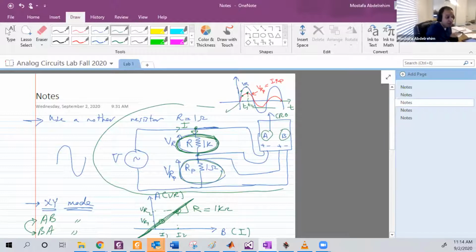And we must put here a variable signal, because we want automatic drawing. So we want the voltage to change by itself without our intervention. We are not doing step by step. So we're gonna choose, for example, a sine wave, because it gives you many points.